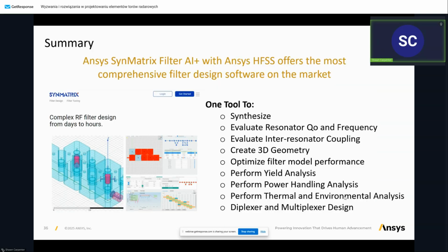Okay, so in conclusion, Ansys SynMatrix Filter AI Plus to synthesize filters, evaluate resonator Q and frequency, evaluate interresonator couplings, create geometries, optimize the filter performance, look at yields, power handling, thermal and environmental analysis, very important, and also recently added diplexers and multiplexer designs.